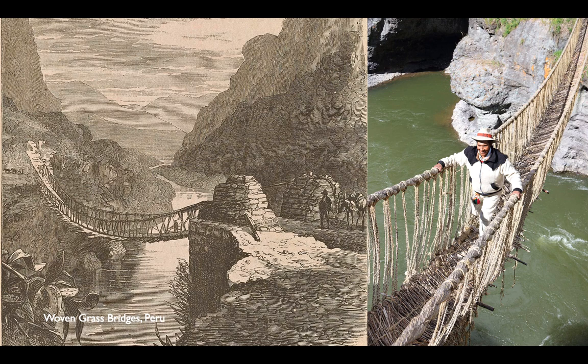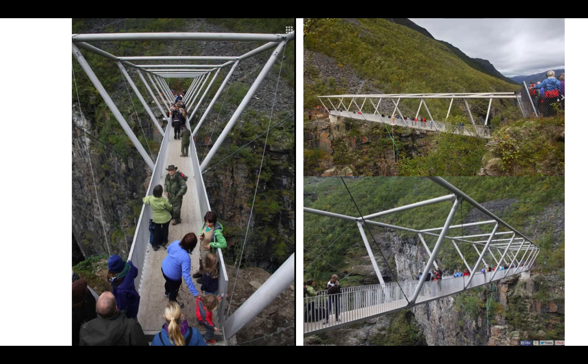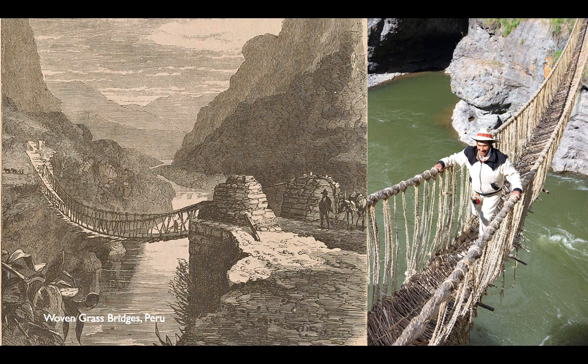Nevertheless, right, these get the job done in similar ways, right? They are perfectly fine for one or two people crossing at a time who are used to walking across bouncy bridges. The villagers in Peru clearly do not have access, or at least not easy access, not cheap access, to steel or to industrial fabrication, or certainly to a helicopter. So this is a very resource and labor appropriate way of getting a long span that probably wouldn't have worked in Norway. Nevertheless, if you look at these two bridges, I'll just go back for a second, you see that the long span is forcing kind of pure structural shapes, right? Triangles, cross bracing in the case of the Norwegian bridge, and this funicular hanging cable shape in the case of the grass bridge in Peru.